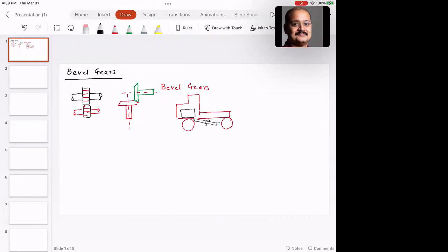On this prop shaft, there is something called the universal joint. A universal joint, just to give you an idea, is sort of a double knuckle joint, wherein you allow articulation at the input side and articulation at the output side. If you look at the design of a universal joint, the principles that you used to design a knuckle joint are applicable. Think of designing a universal joint like designing two knuckle joints.